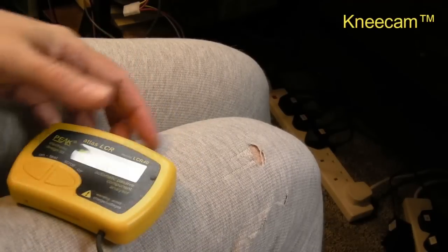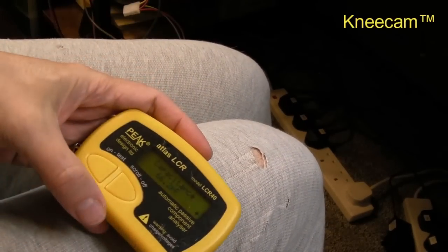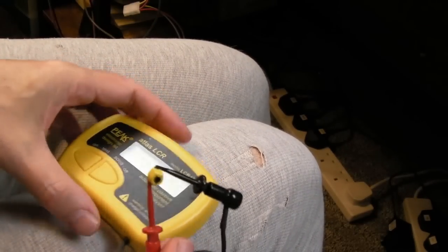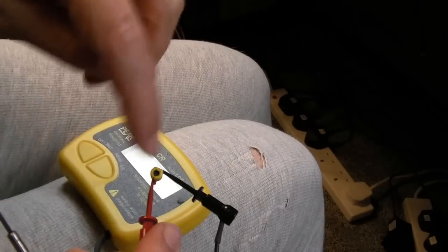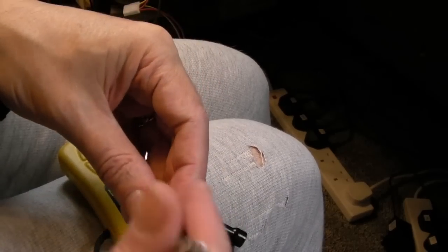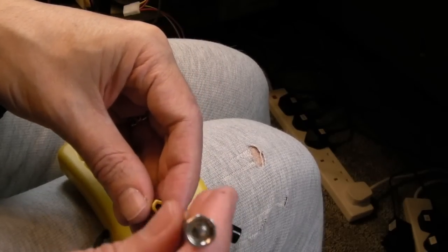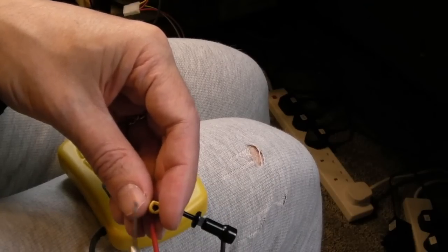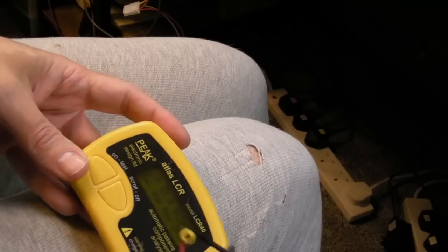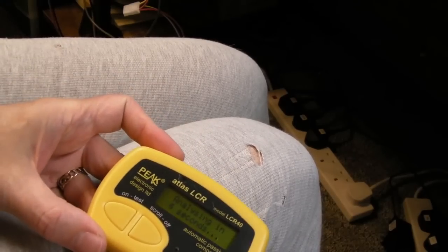So yeah, you can see the holes in my pants here. Yeah, you can see I also just got some vinegar in this, soaked it for about half an hour actually, flushed it out with IPA and then tried to turn it. It was pretty jammed. Got some DeoxIT in there, so it freed up, more DeoxIT and more DeoxIT, flushed it out, and yeah, you'll see it looks nice and clean on the inside, but it actually works.